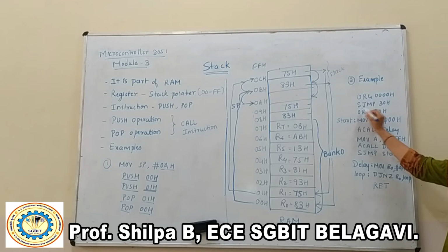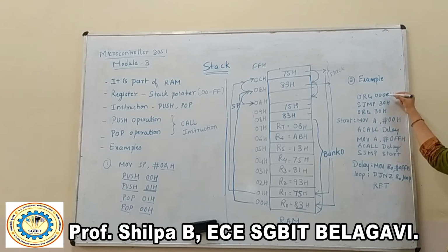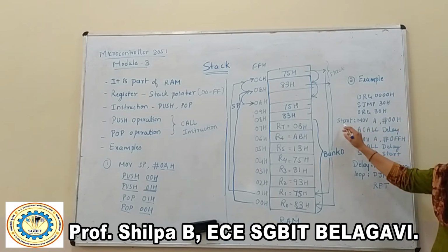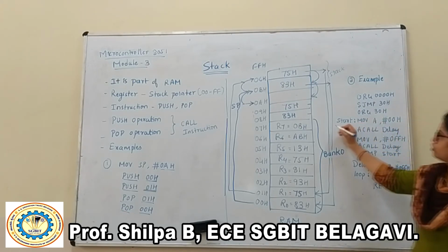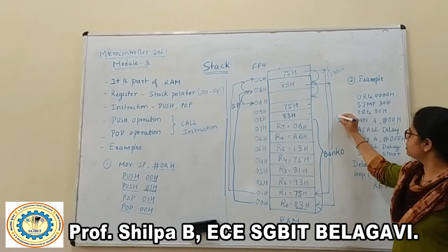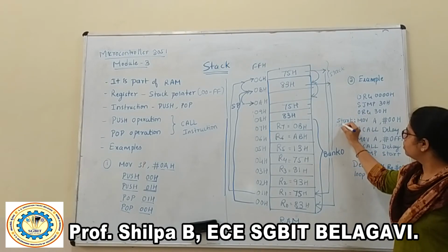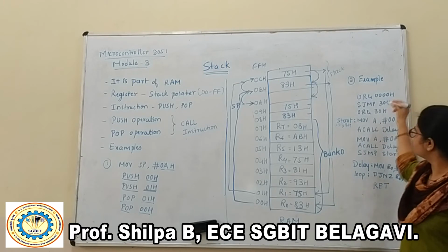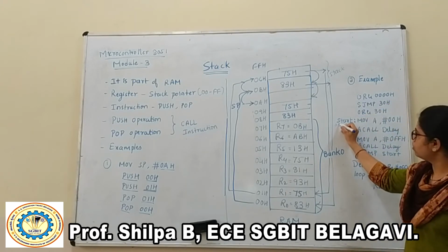I am going to jump to 30H, because from 0000 to 0030 some interrupt programs, the ISR addresses, are going to be loaded. For that reason I jump by 30 and fix my origin as 30H. So the address of this instruction is 0030H, because it starts from 0030H.